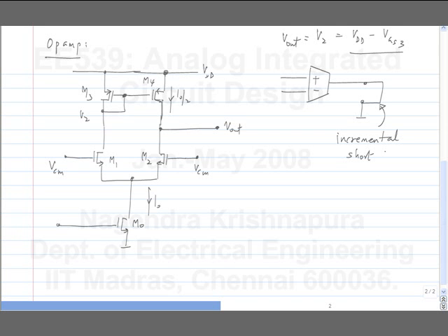Yeah. So what value? What's the value of the? So if I connect this to, this would be at VDD minus VGS3. Okay. I connect it to a voltage source of value VDD minus VGS3. Let's assume that somehow I have measured this or calculated it and I connect it there. So this will not disturb the bias condition in any way, but it will terminate the output with an incremental short circuit. Okay. Is this clear?